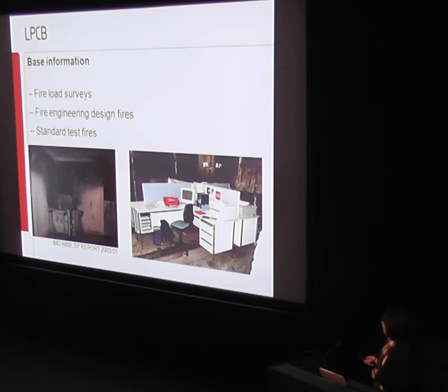We also looked at standard fire tests, which have come from the IMO arena. They don't always present the most challenging of tests. They present very open surfaces that the water can get to with small amounts of obstruction. The corner test, to some extent, is quite good because you can get vertical spread as well as horizontal spread. But it's a very exposed test from the perspective of water mist.